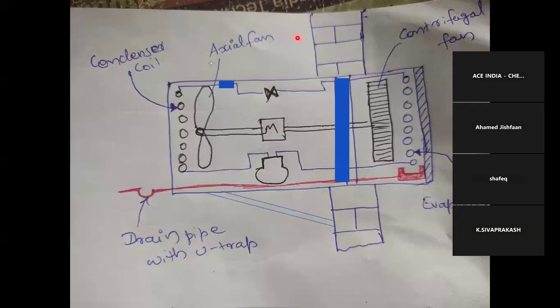Cold air means it has high density, isn't it? So if you swap this axial fan right in front of this evaporator, your room will not be getting cooled properly. Or in other words, the air will not reach the extent of your room. Why? Because it's simply pushing the air in a slow manner, isn't it? But typically on the evaporator side, we need more throw. For that, you need more push to the cold air to those rooms.